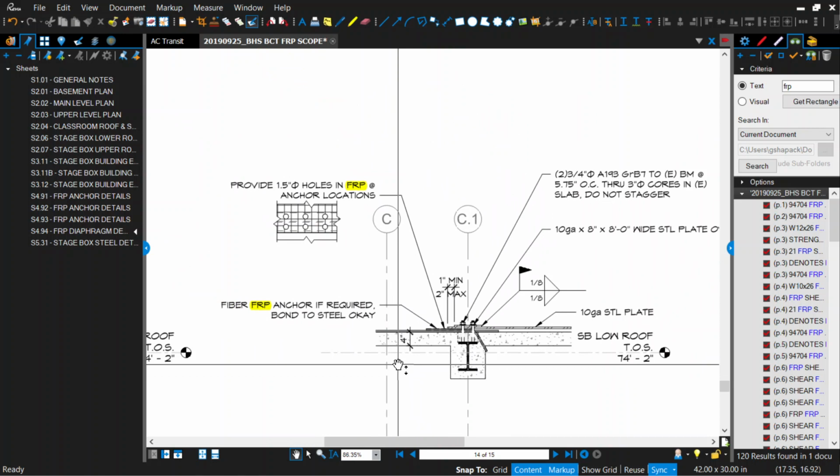Because we're not doing L-shaped, we're allowed to design it, I guess the new train of thought is shear transfer, but shear friction, sorry. So that's what we need to do at that detail to be able to come up with a design, and we'll probably have to add several layers of FRP to get it to work. Is that the one that you showed me in the shear transfer trainings? Shear friction, converting from tension to shear. Yeah, exactly.